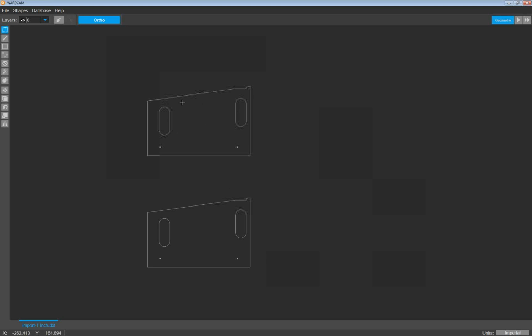And then I might want to spin this part around. So again, I can select what I want to work with, and then I can use my rotate command. And again, I'm just going to approximately click in the middle here. And again, down at the bottom, select rotation point or use keyboard for input. So if I wanted to rotate it 30 degrees, I could type in that. Since I have my ortho button turned on, as I move my mouse around, it's going to snap to the different 90-degree rotation points. So we're going to rotate it like that.